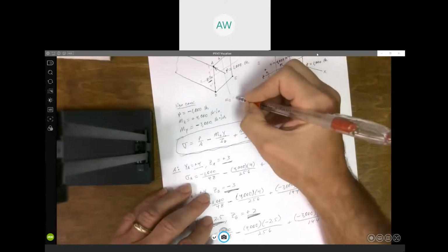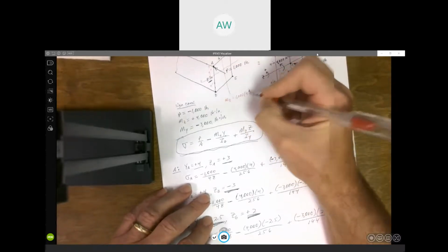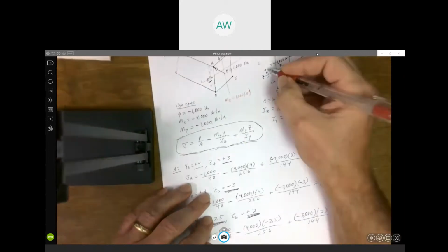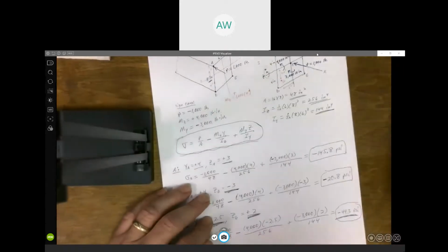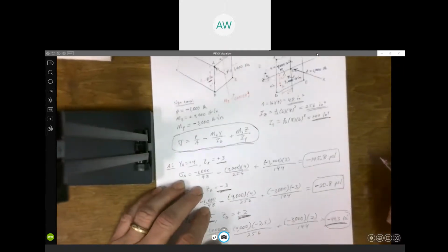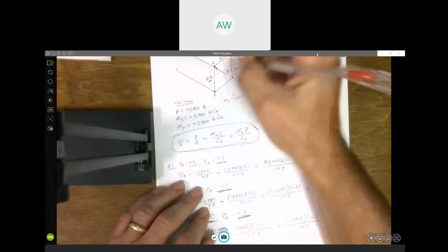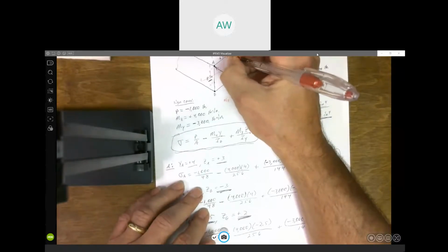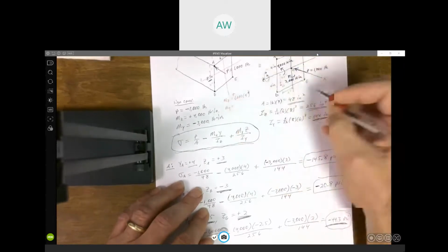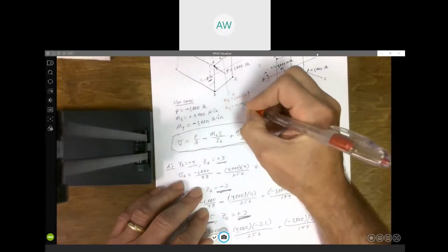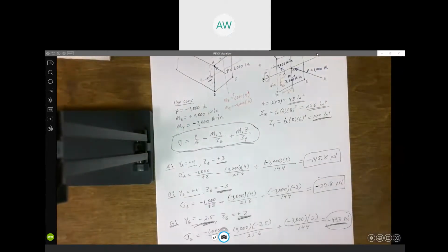So it would be 1,000 pounds times 4 inches. And if this is defined as positive, that's a positive moment. It's just the force times the distance from the axis. Gotcha. Same thing to get the moment about the y-axis. We took this force times the distance away from the y-axis, which, based on our sign convention, is negative, right? And that distance was 3. Right?